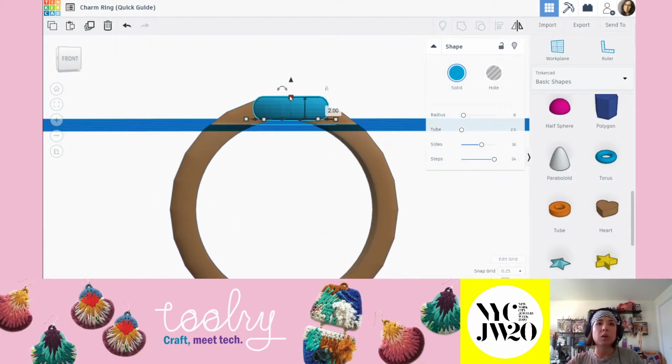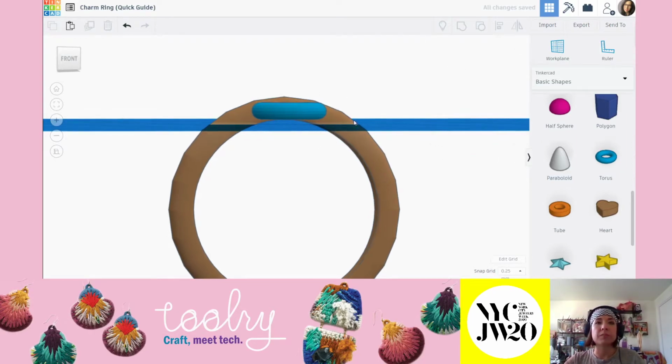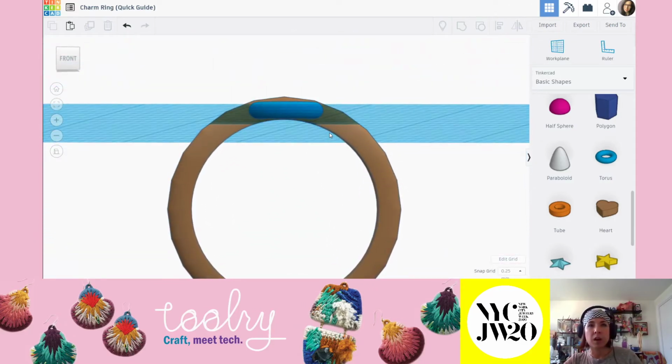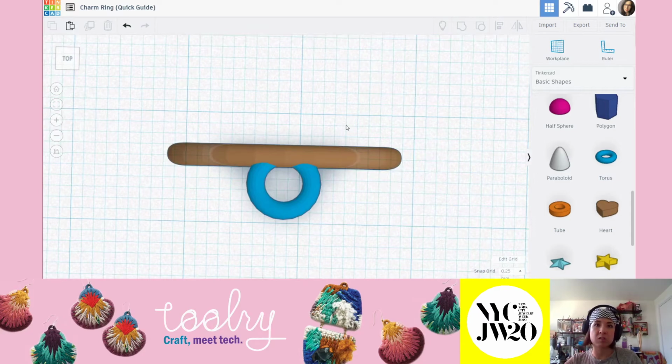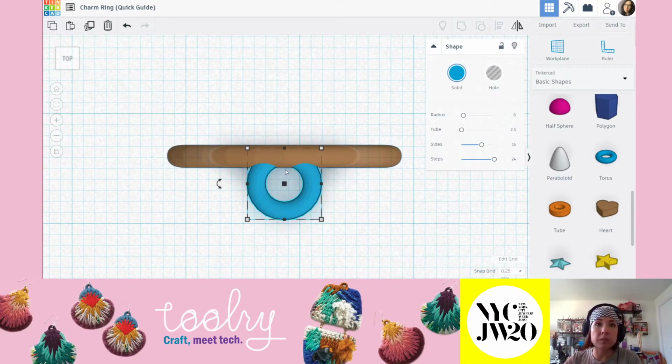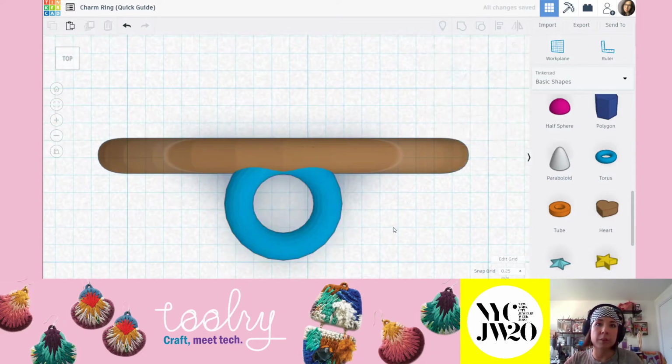Okay. So if you were following along, this is actually supposed to be 1.5, not 2. That was my mistake right there. Sorry about that. I was thinking it looked a little bit thick. So yeah, 1.5, and that should resolve any kind of surface collision issue that you're having. And then let me just double check. I can see that I've accidentally, there we go. Perfect. So my entire cutout is showing.